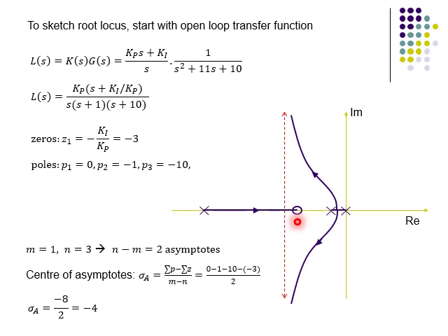So you can see that as we increase Kp, the two poles on the right side here will follow the branches, which become complex here and here, and this pole at -10 will move to the right, and for very large Kp will approach the value of the open loop zero.